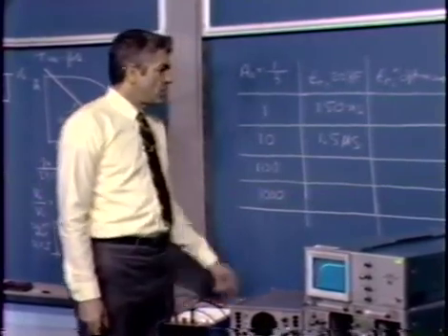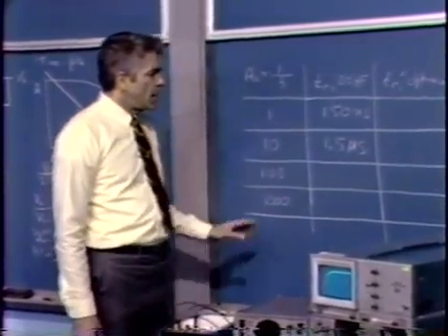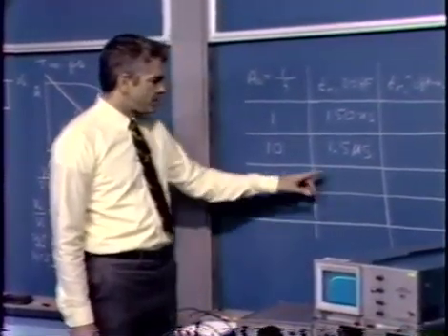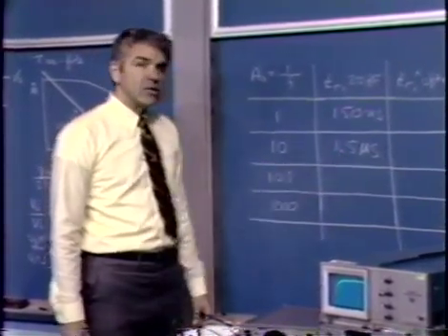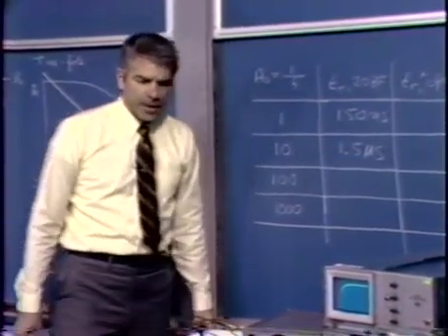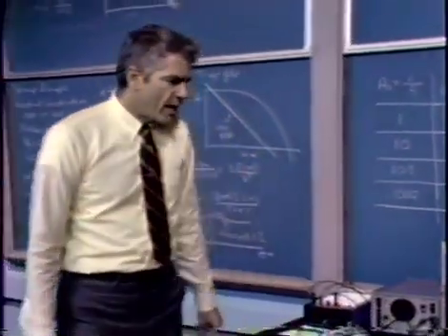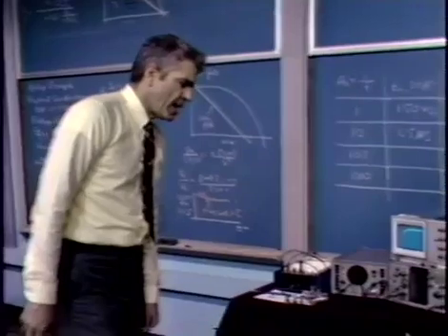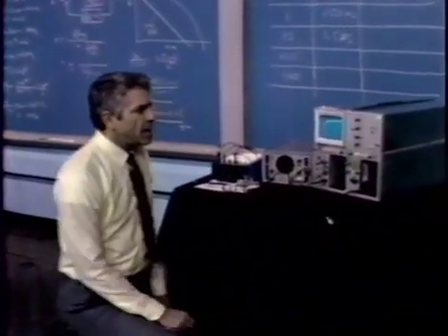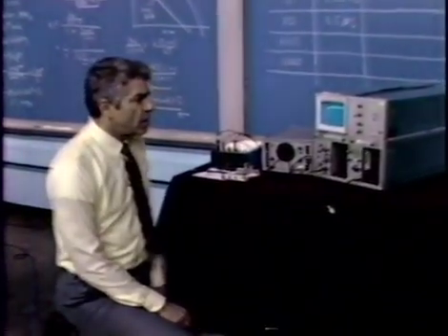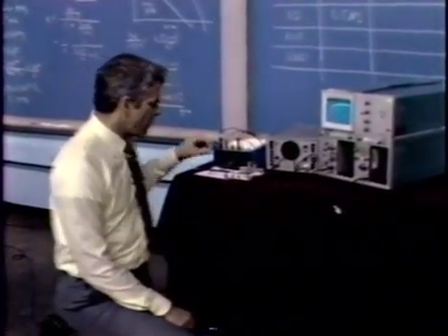The original response, this one, had just a little bit of overshoot. Once we are observing this response, we noticed it looked very, very much first order. However, we have lost the factor of 10 in response time or in bandwidth, and we can buy that back by lowering the size of the capacitor by about a factor of 10.